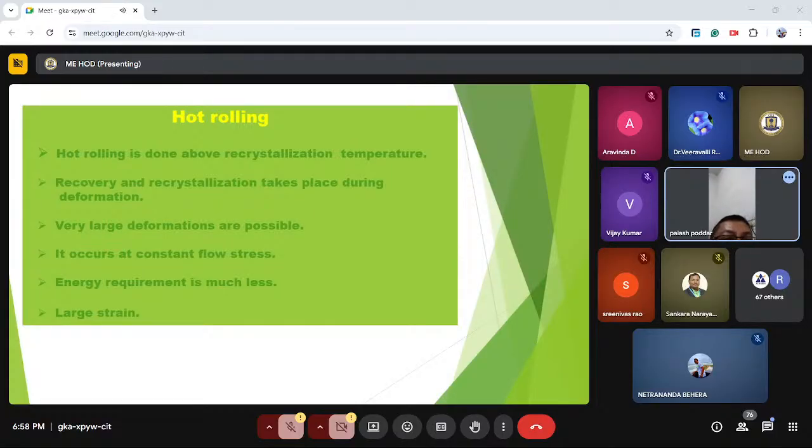Next. Now see the hot rolling process or stages. What is the process for hot rolling? The hot metal is coming from the furnace or from the converter. It is taken through a ladle to a continuous caster. Through the tundish, it will move and a torch cutter will be there that will cut out the slab, and the soaking pit will be here, where it will be softened, and then it will go for the slabbing mill.